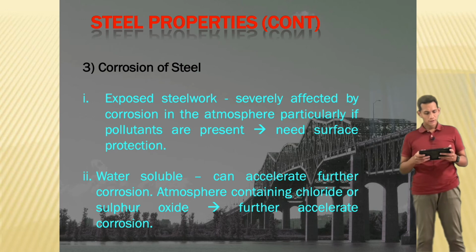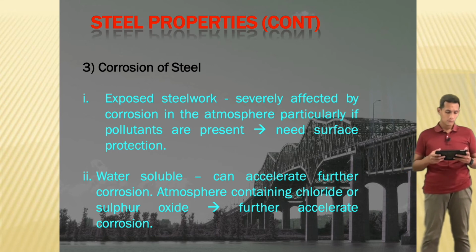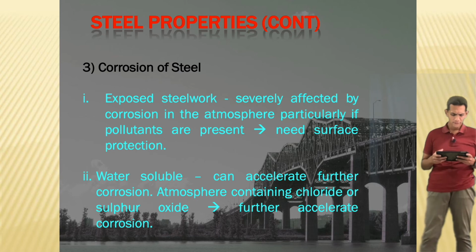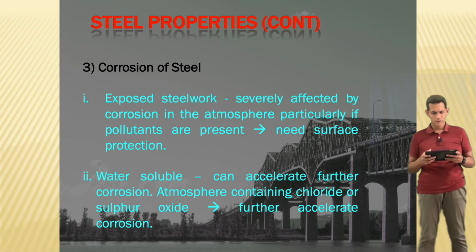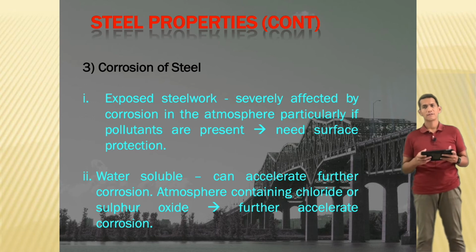Number 3, corrosion of steel. Exposed steelwork is severely affected by corrosion in the atmosphere, particularly if pollutants are present, and this needs surface protection. Water soluble salts can accelerate further corrosion. Atmosphere containing chloride or sulfur oxide further accelerates the corrosion.